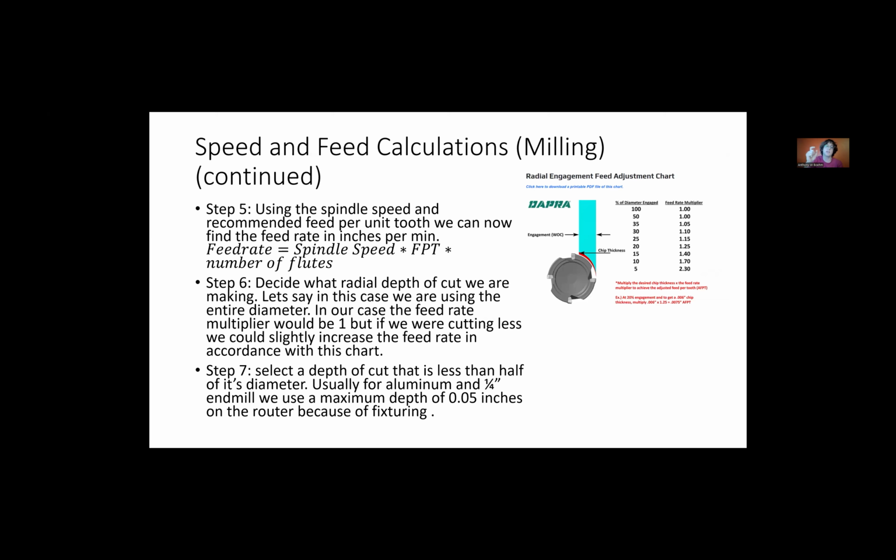You could use that value to tune the depth that you're cutting with your feed rate. You could figure out the swept volume of your tool as it cuts to figure out how much depth you could afford to use with that particular tool with given specifications. Now that concludes our presentation portion, and I will go over to our examples.